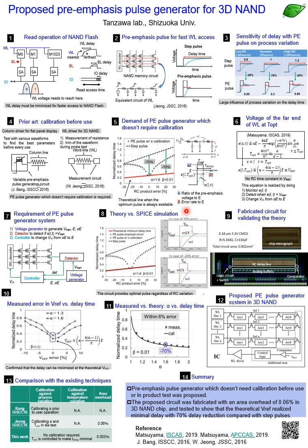These two waveforms show the farthest node and 1/3 of the word line in the case of plus 20% and minus 20% variations. As you see, the voltage approaches the target voltage at the farthest node and 1/3 symmetrically.